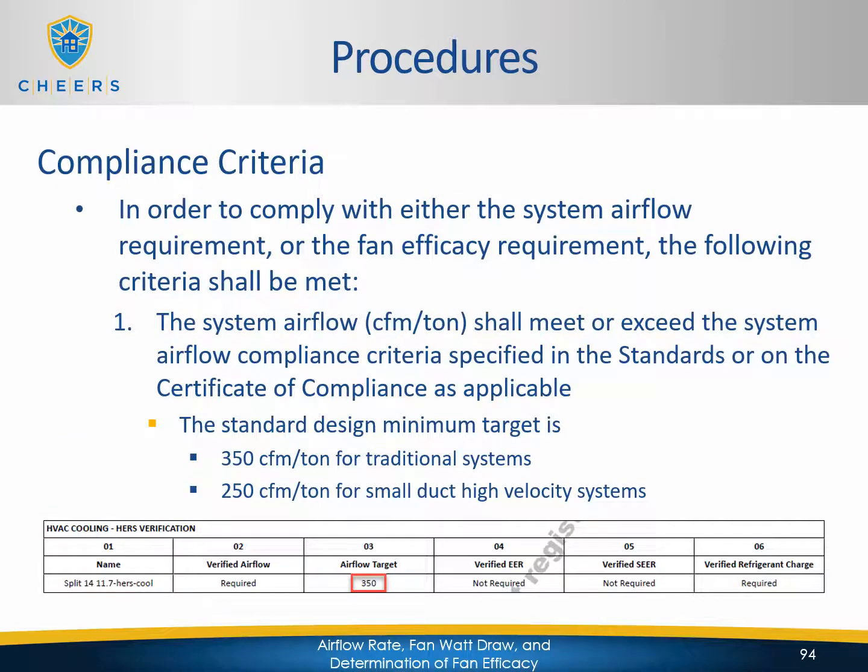So now that we know how to collect and calculate the data for both airflow and fan watt draw, let's look at the compliance criteria. In order for the system to comply with either the system airflow requirement or the fan efficacy requirement, the following criteria shall be met. The system airflow, which is CFM per ton, shall meet or exceed the system airflow compliance criteria specified in the standards or on the certificate of compliance as applicable.